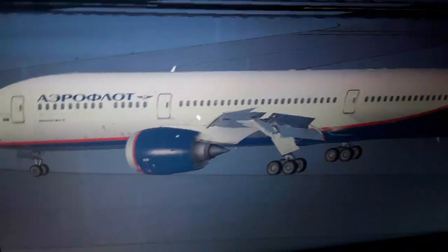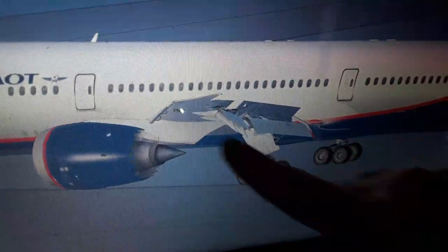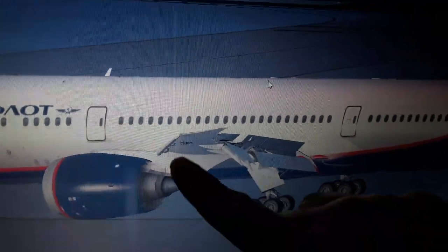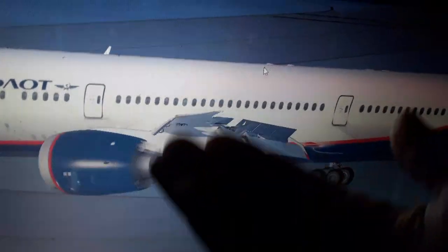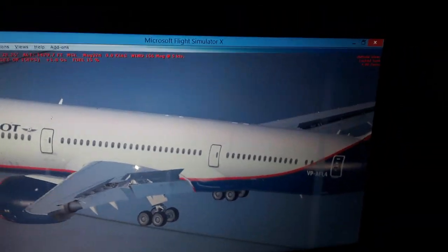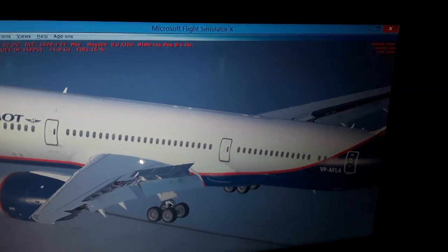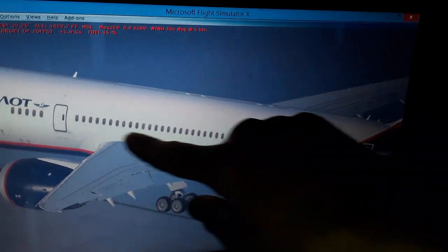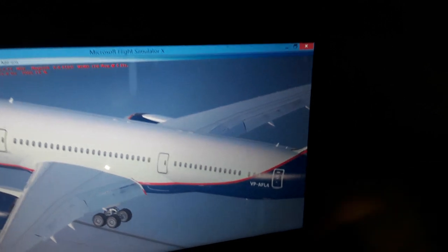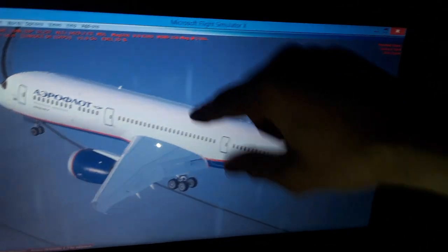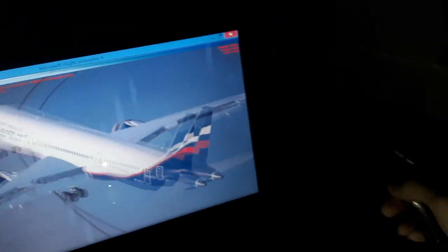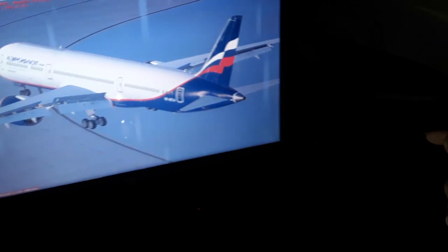As we accelerate to around 250 kilometers an hour, we have lower airspeed below the wings, so higher air pressure, which pushes the aircraft weight and wings up into the air. Also you can see the top surface of the wings is more curved, higher curvature, so the airflow moves much faster above the wings, which creates lower air pressure, using Bernoulli's principle of fluids. Lower pressure above and higher pressure below the wings creates the aerodynamic lift, which sucks the aircraft weight and wings up into the air. So we have a few more things to see.